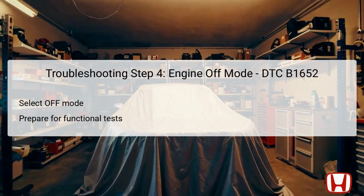Selecting the off mode is a necessary step in troubleshooting DTC B1652, ensuring that the vehicle is in a safe state before proceeding with the next diagnostic steps. By pressing the engine start-stop button, technicians can effectively power down the vehicle and reset the electronic systems momentarily. This process helps in stabilizing the system for accurate readings and reactivates any dormant components. Once in the off mode, it prepares the technician to perform vital functional tests safely and effectively.